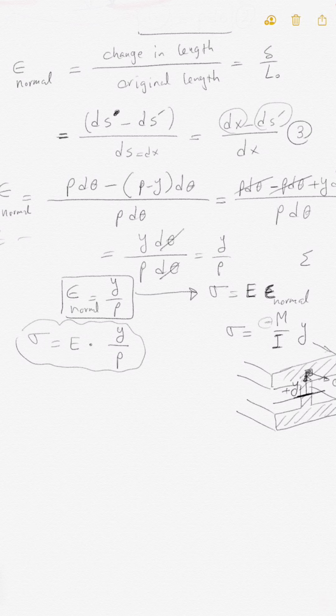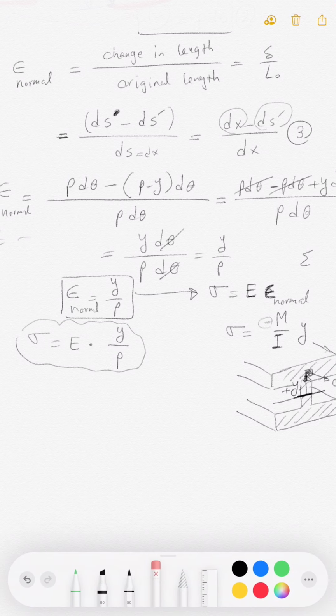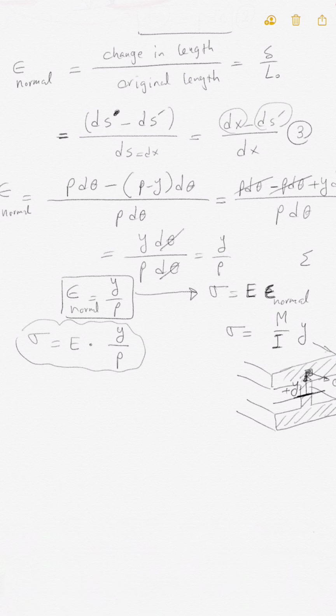So basically it's all about the negative sign that will cancel anyway. So let me clean up these things here, and I write this formula. So I had this formula long time ago. This normal stress at any point at y is equal to the moment, and what was the moment? The moment in that cross section divided by I.